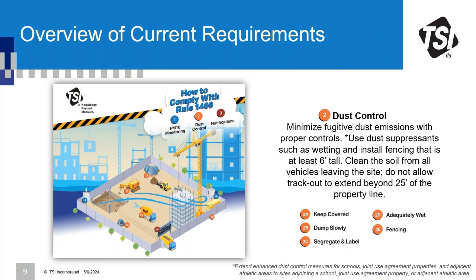Dust control measures. So let's say you do have an exceedance of the dust, you have to do some suppressants. So you have to either use water, wet down the areas, install fencing at a certain height, and from there cleaning the soil from the vehicles that are leaving. So there's a couple different methods for mitigating the dust that's leaving the site.